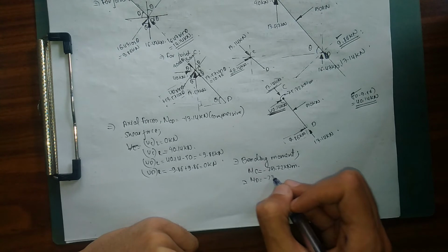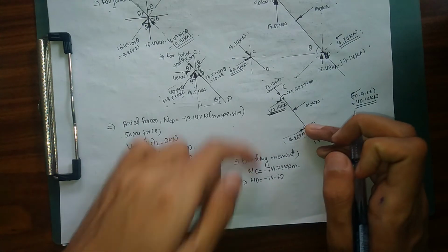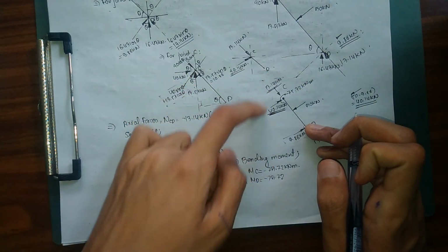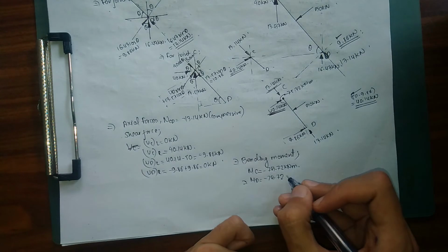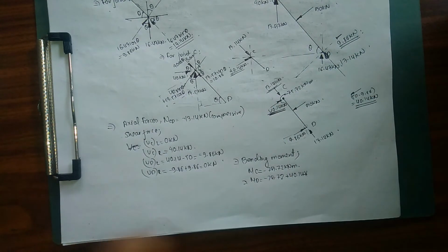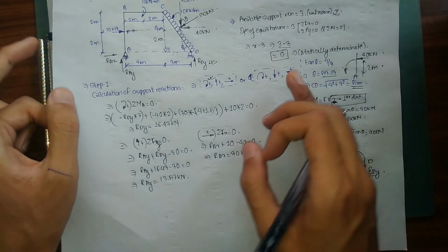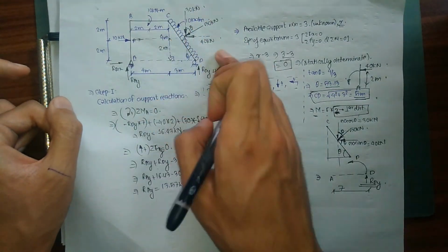As we move a little bit, now I'm going to get my bending moment about D. Bending moment about D is 75.72. So next we have this 40.14, and 40.14 is producing clockwise movement with respect to point D, plus 40.14 into my distance, which is 5 meters. I calculated this in my first. Here is my length CD, it is 5 meters.